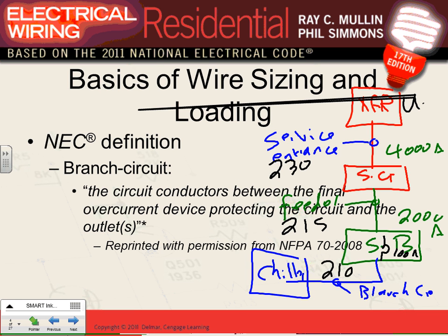Now, in this project we have an apartment building with a transformer. We're going to bring the power to the apartment building in a meter center, and we're going to distribute the power to every apartment. That will be the feeders. And inside every apartment, we're going to have a branch circuit that goes to all the receptacles and all the lights and all the HVAC equipment. Everybody's okay with this? Understand the big picture? That's what they call risers and one-line diagram that we're going to be moving on.